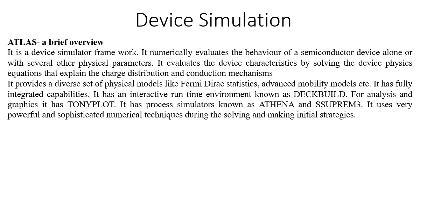It also evaluates the electrical characteristics, conduction mechanism, and charge distribution. It provides a diverse set of physical models like Fermi-Dirac statistics and advanced mobility models. It also has fully integrated capabilities, like another runtime environment on which we can easily visualize the results